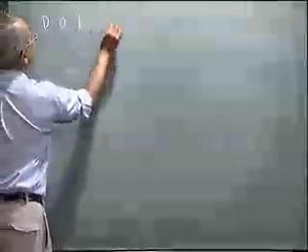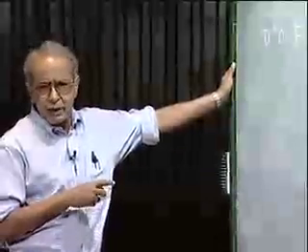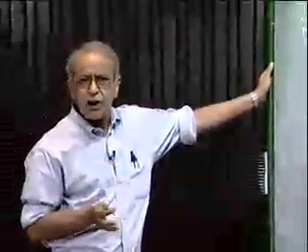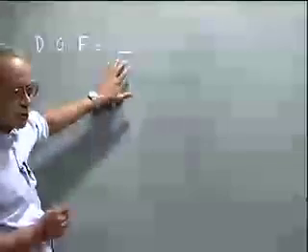But when we come to epicyclic gear chain, what we have noted is that epicyclic gear chain has 2 degrees of freedom. Degree of freedom is 2, which means 2 input speeds need to be specified to determine all other output speeds. Conversely, if there is only 1 input, then I can get 2 outputs which can be adjusted because you have to follow one relation, but you cannot determine exactly what will be the output speed. That is the degree of freedom is 2, and which has a lot of applications as we will see later